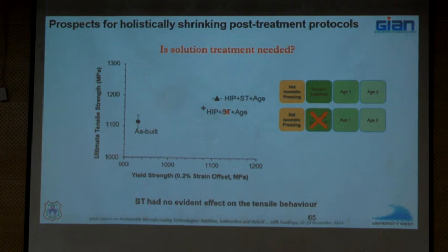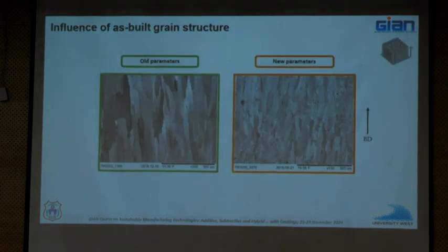Now we are also getting a little bit greedy, trying to see, do we even need solution treatment if you are going to HIP at 1120 degrees for an hour? Can we skip solution treatment also? So that is our data at the moment. If you eliminate solution treatment, we don't really know whether this is acceptable to the users or not. But this is for a specific material system, and I would like you to think along those lines, right?